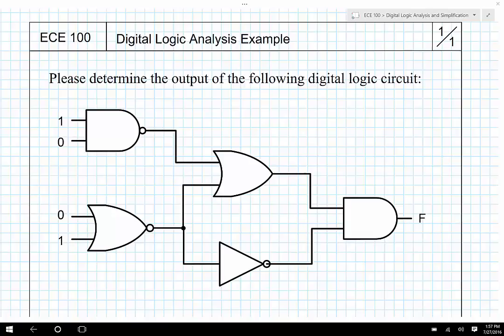You can see here, if I first of all just think about what would be the output of this gate if it were just an AND gate. So I'm going to look just before the bubble, just before the inverter. If I'm ANDing together 1 and 0, well, that's going to yield a 0 because it has to be 1 and 1 in order for that to be a 1. But of course, once it gets inverted, this location is going to have a 1. And of course, the wire that connects that gate to the next gate is just going to faithfully transmit the signal that was applied to it. So a 1 will be applied to the input of the OR gate.